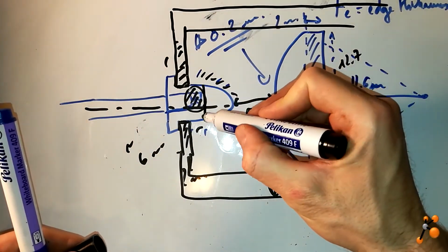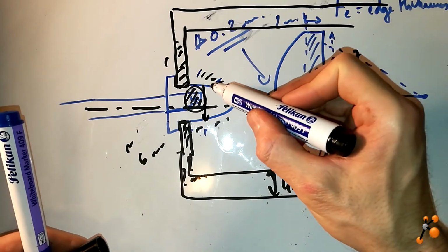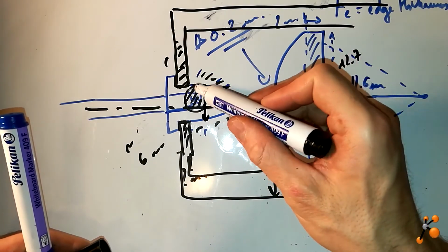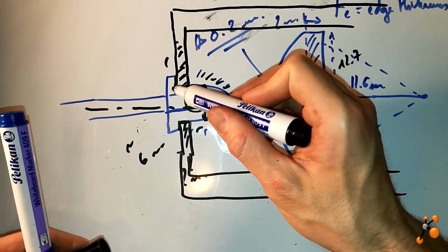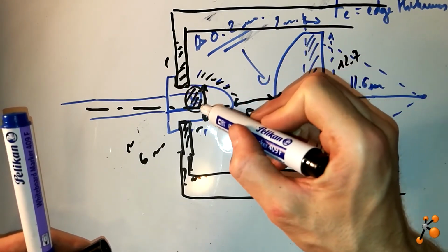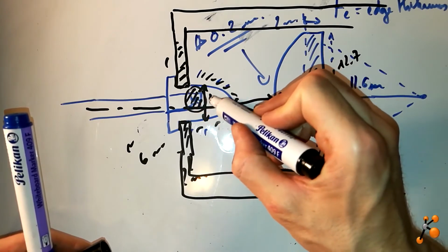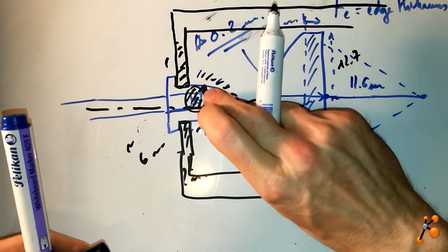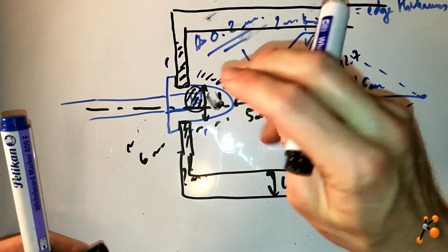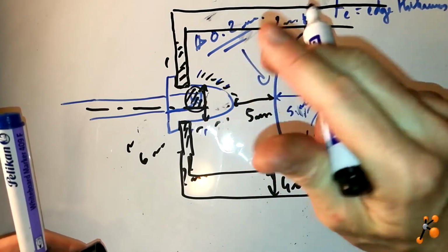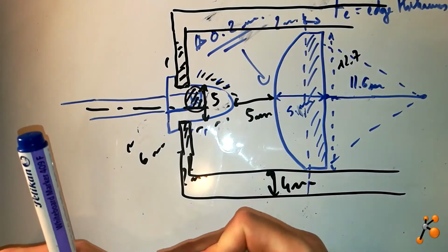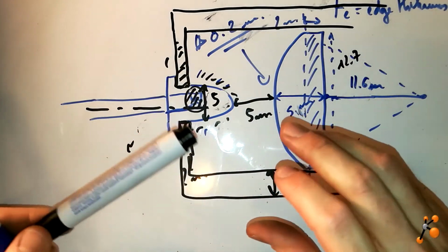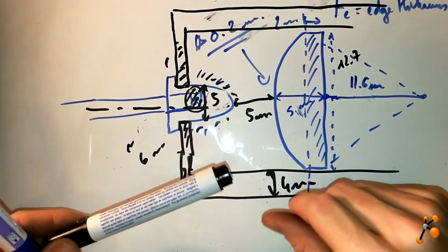Here we have the diameter where I will insert. So this is an important diameter that we should be careful. It's 4.8, but we will put 5 to simplify the system, because anyway the printer is not really precise. You have some difference, as I told you, 0.1, 0.2 you have to consider.